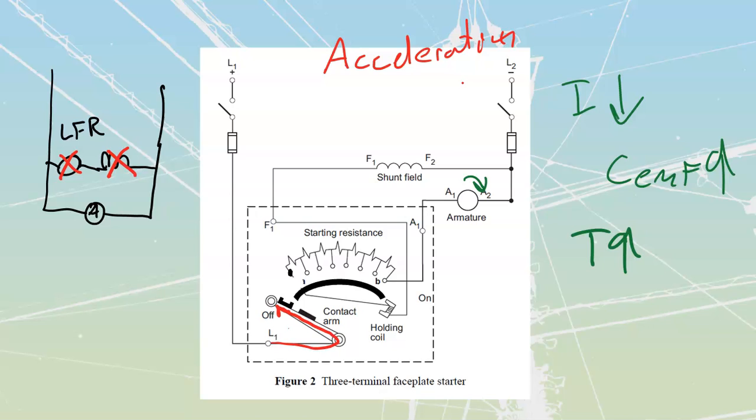I think that's it for anything I want to highlight off of this one. As far as shutting this motor off, by the way, all you would need to do is provide a little bit of a tug backwards off of this thing. If you give it just a little bit of a tug, you're going to break that magnetic contact over there. It's not a super strong magnetic contact. And then the spring action would pull this thing back down through, and it'll actually give you a little bit of deceleration on the motor as well.